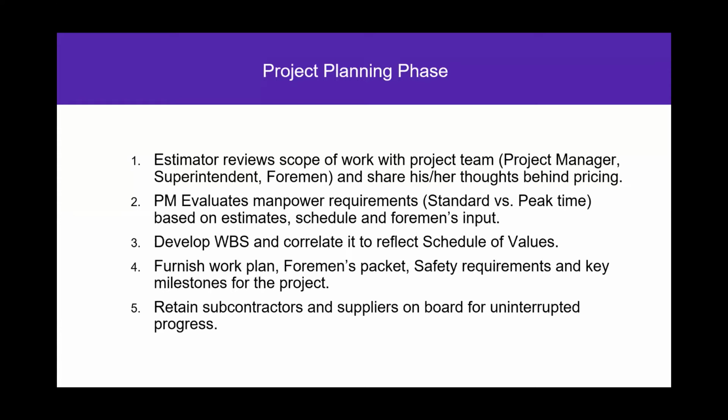Right now this is my crew size, and if I had to upsize my crew to meet the schedule, that's how I'm going to do it. So it's either determining if I'm going to work 5 8-hour days, or 5 10-hour days, or if I need to double the crew, depending upon the type of the project and the general contractor's requirement.